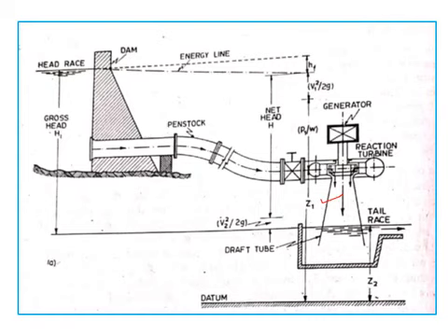So we have seen that the lower part of the draft tube is dipped in the tail race. Okay, so here it will be atmospheric pressure. Since it is dipped and here we have atmospheric pressure, generally it is seen that the pressure at the inlet of the draft tube is always negative, so this will enable us to install the turbine at a higher level.